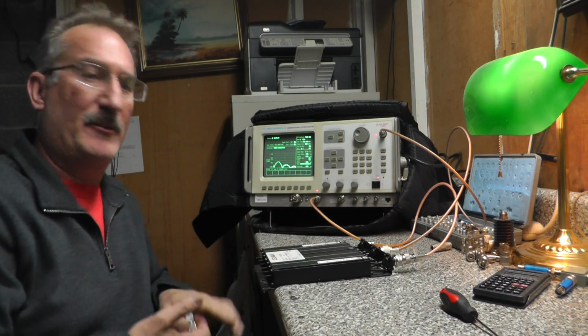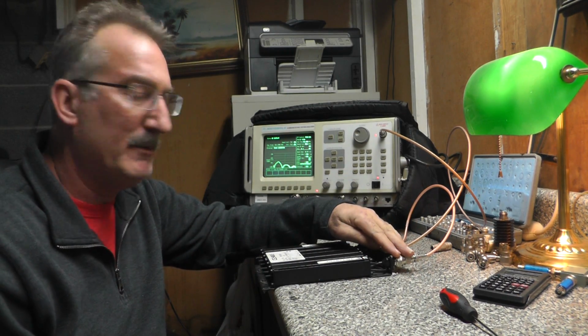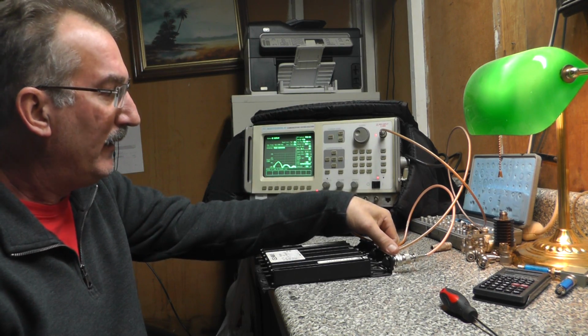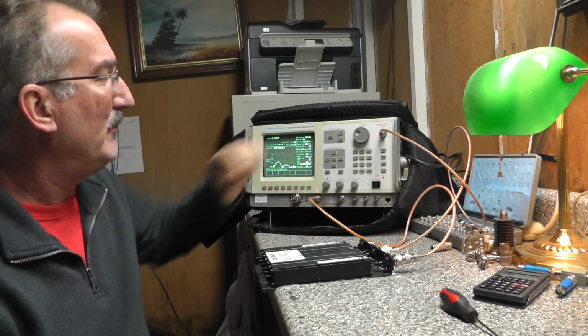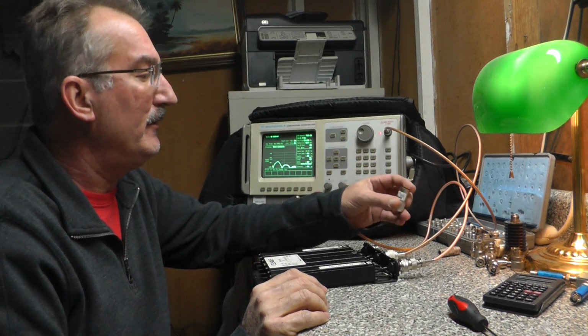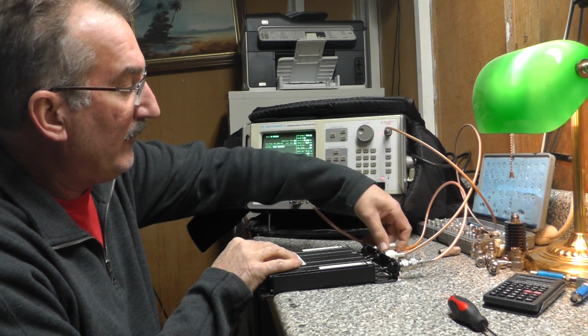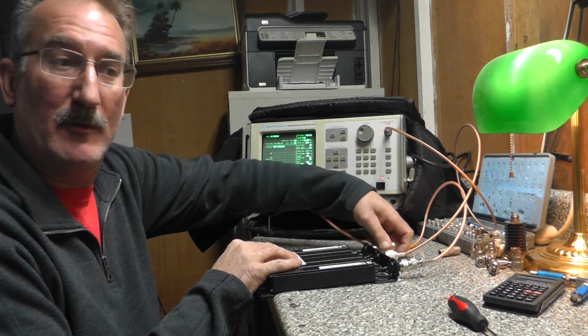So at this point what I've done is I've connected my RF source to my transmitter input, and I've connected my antenna port to my antenna port here to detect that power. And I'm going to add this 50 ohm termination over here to the receiver port to give us some impedance matching.